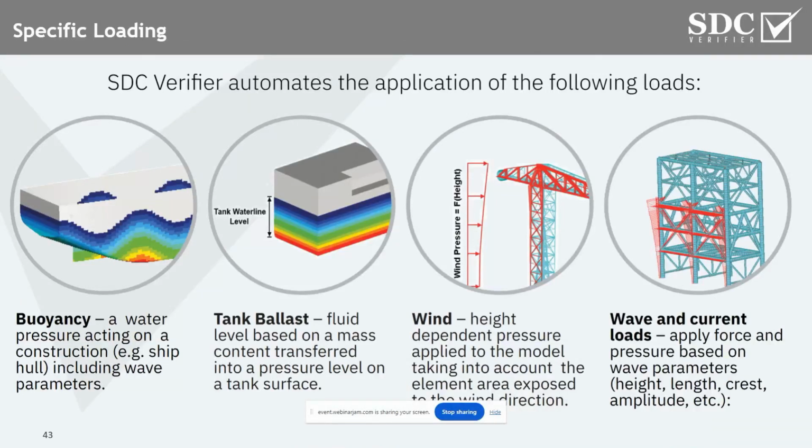For example, starting with wind load, which I mentioned before, wind is actually crucial when checking port equipment and especially cranes. At out-of-service conditions, old standards say that we have constant wind pressure and wind velocity over the height. That is a relatively simplified and conservative approach. However, more harmonized standards like EN 13001 say that the wind pressure is increasing with height.